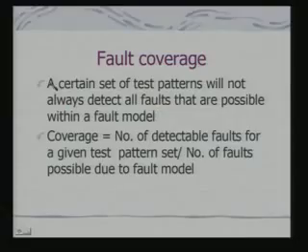Related to this is a concept called fault coverage. A certain set of test patterns will not always detect all faults that are possible within a fault model, because that is not always possible. Then the number of test patterns that you need to use can become very large. So, we have to select a set of test patterns which will detect the different faults as suggested by the corresponding fault model.